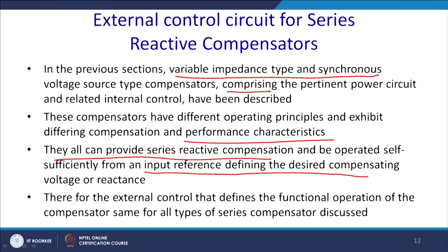Therefore, the external control that defines the functional operations of the compensator is the same for all types of series compensator discussed. Ultimately, it will inject some amount of var to the system. So, whether it is the impedance method or the voltage method, externally they look equal.